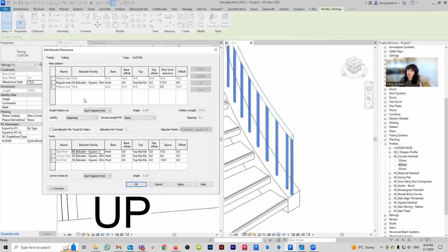When you're thinking about your balusters, your vertical elements, you have to think about them in two broad categories. Number one is the important points of the stairs, which are these three guys here. This is what you're going to have at the beginning of the stair, at the end of the stair, and anytime the stair changes direction. For example, if you have a corner or a landing. And then you have everybody else, because you can have a railing where you have different kinds of balusters interconnected, all assembled together. That's why you can see that you have this element and then this element here.